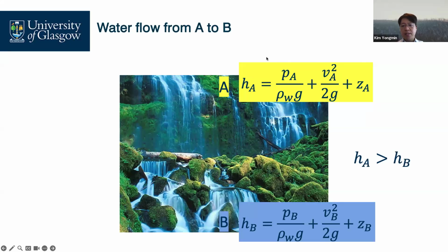This pressure head is the water height of the standpipe, represented by the water pressure divided by the unit weight of water. This pressure head is the water pressure. How do you get the water pressure? Unit weight of water times water height. How do you get the water height? You can install your standpipe, then you can see the water height. This is the pore water pressure.